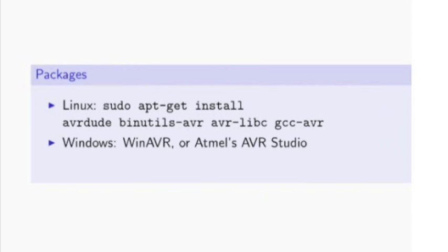They also secretly put out a new and constantly updated compiler tool chain that doesn't use the integrated environment, but you have to root around for that. You can't lose with either WinAVR or AVR Studio, depending on whether you want to type make yourself in the case of WinAVR or use an integrated development environment and press a button in the case of AVR Studio.